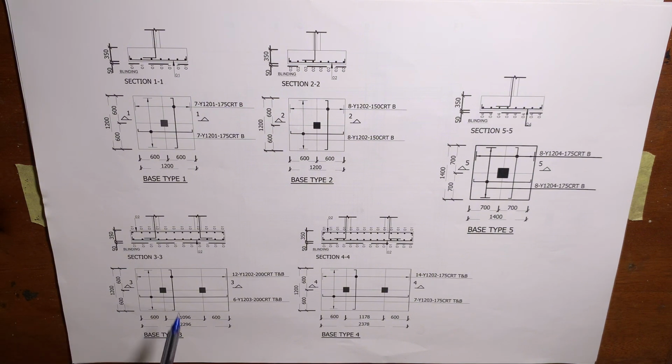So now let's look at the reinforcement details, starting with the vertical bar. Now if you look at the vertical bar, this is bar mark 2. So you can now see that the number of this particular base type for the reinforcement is 12 in number. They are going to be using 12 mm reinforcement, and look at the spacing. It is at 200 center to center. And look at this, the reinforcement is both at the top and at the bottom.